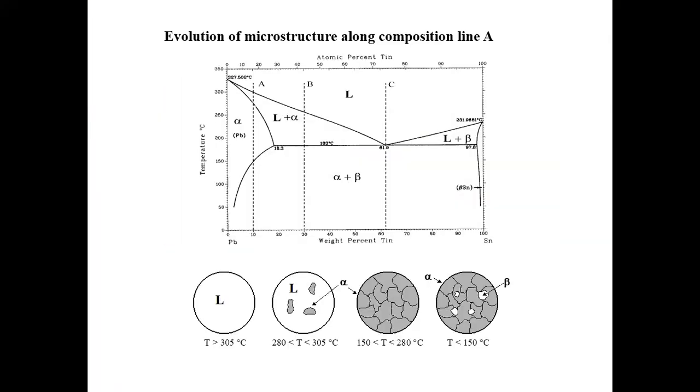What we have been focusing on is this particular branch of the phase diagram. If we choose a low composition alloy, we have analyzed the liquid-solid transformation, and now if we push into the even lower temperature regime, we're looking at the nucleation and growth of the precipitates.